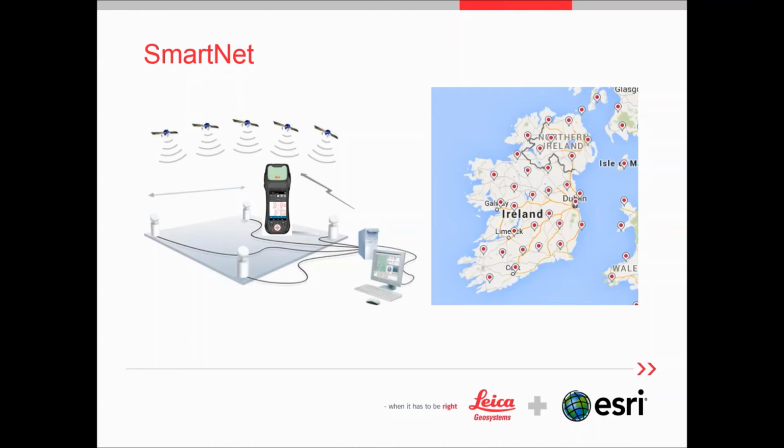10 years ago, RTK surveys typically involved 2 GPS receivers, a lot of batteries and cables, 2 radios, a tripod, a pole, and a backpack to carry it all. Today, with Zeno Collector, you can access the SmartNet network over a mobile data connection to work with RTK corrections in the field, instead of setting up your own base station, saving you time and money.